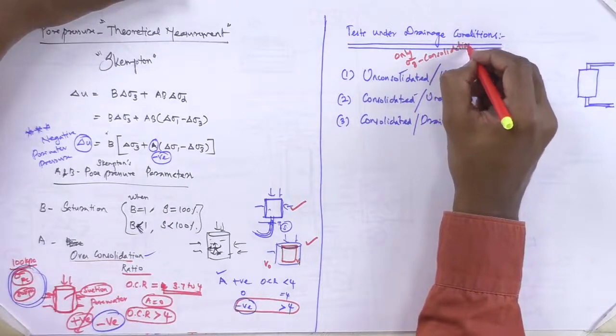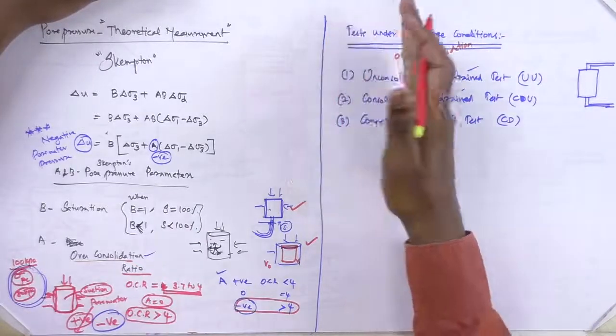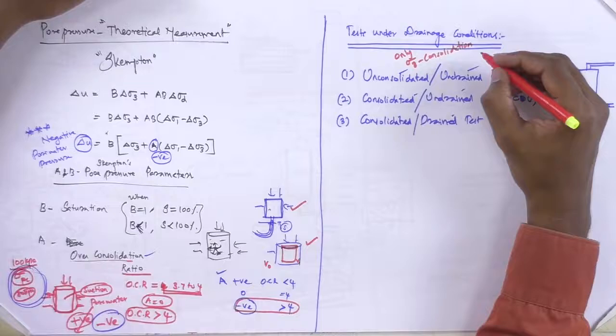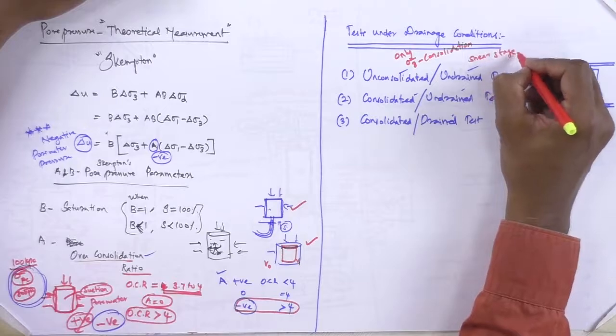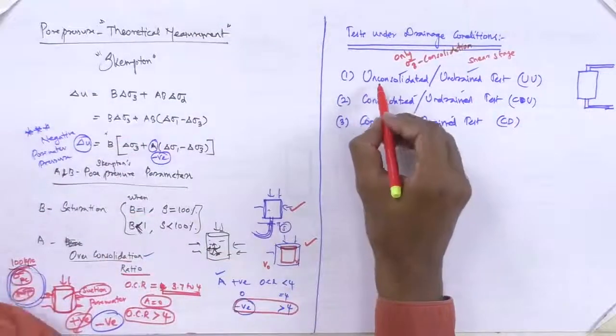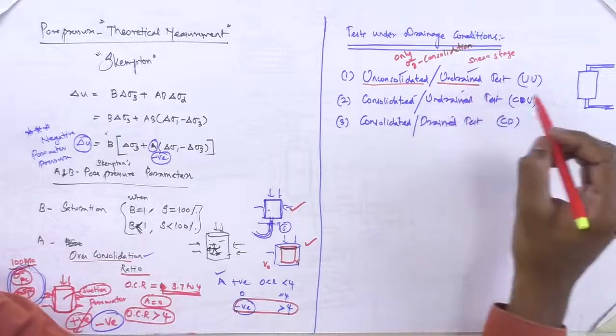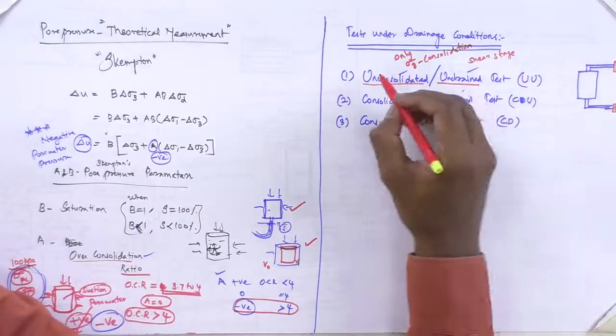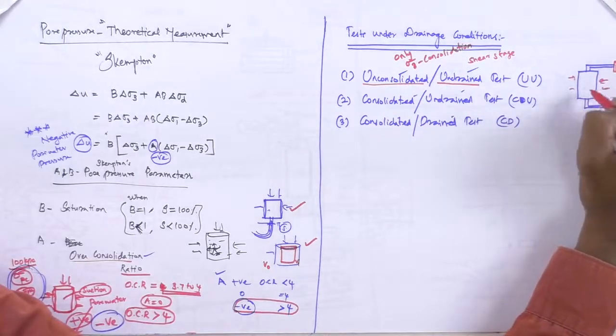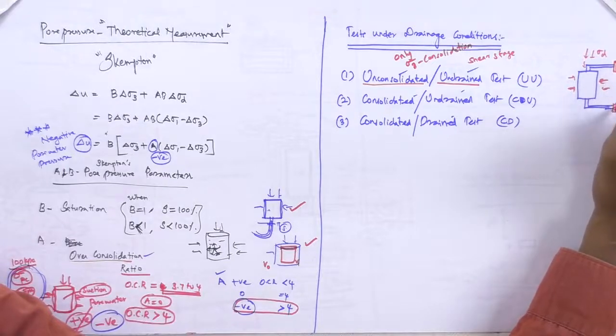it is the consolidation process. Once you allow the consolidation process, then you can start the shear failure. So this is the shear stage as explained earlier. So I can split this in 2. So this is unconsolidated undrained. So this is a pore water pressure valve. So we have an open-close valve. So when sigma 3 is applied, whatever sigma 3 is, and we are applying a sigma d. During the application of sigma 3 in all directions, this pore water pressure valve is closed, which means you are not allowing the water to go out of the system.